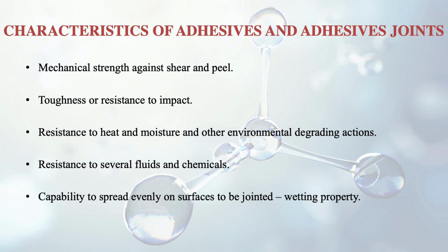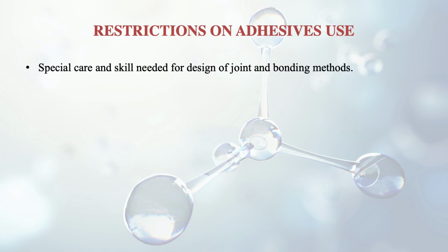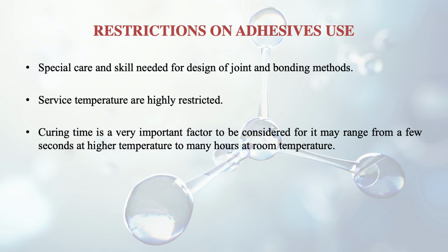And what are the restrictions on these adhesives' use? We need to be very careful while using these, because skill is needed for design of the joint and the bonding methods. And the service temperature, we know we cannot use it in very high temperature applications, it is restricted. Then curing time is also a very important factor, because it may range from a few seconds at higher temperature to many hours at room temperature also. So this is an important factor.